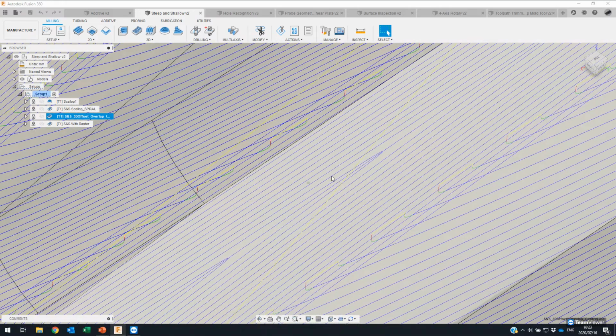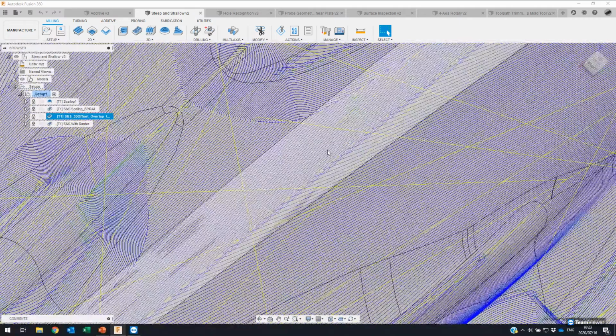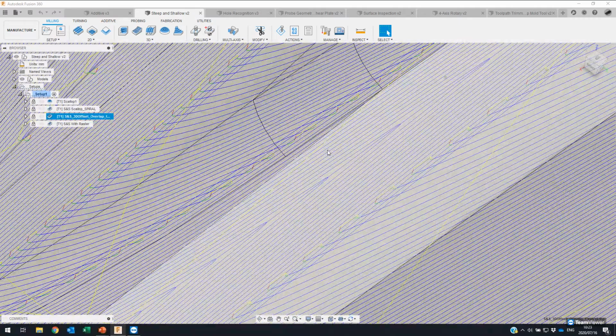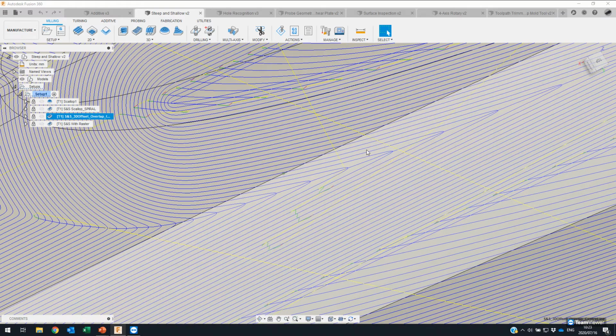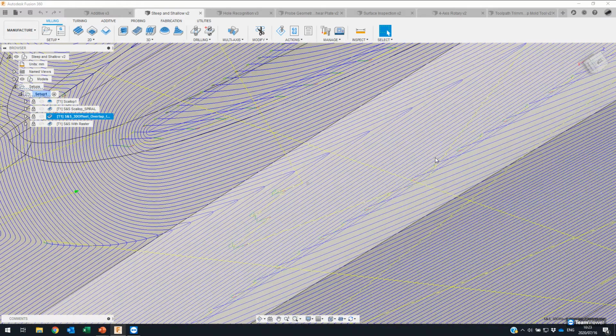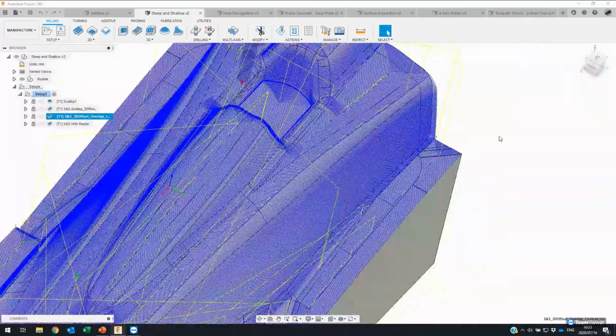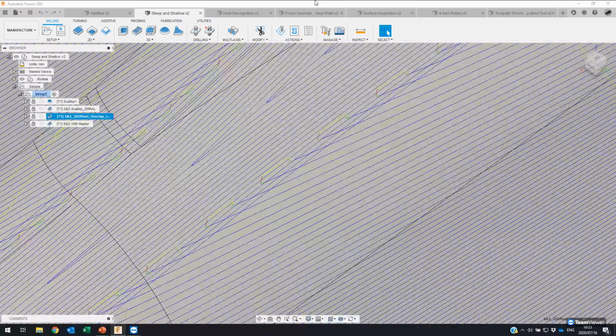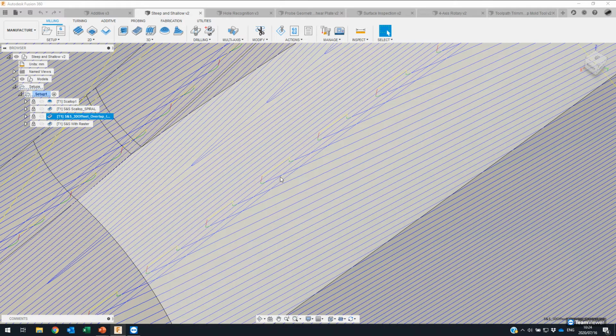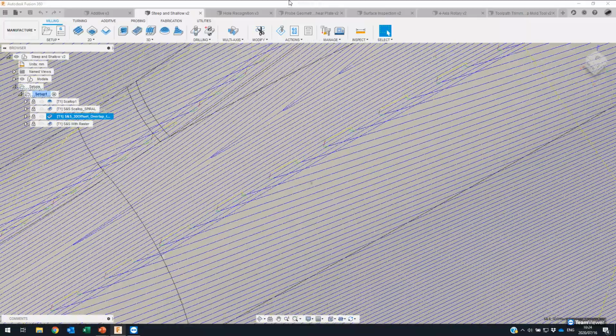And once again, if I zoom in on that toolpath, we can see, let me go to a section where it's a little more obvious, at each of these apexes where it turns, there is that toolpath flowing through those apexes to remove those cusps. And we also have overlap between the toolpaths. We go over here. We can see overlap between the parallel, or this steep and shallow toolpaths across the center of the screen here.